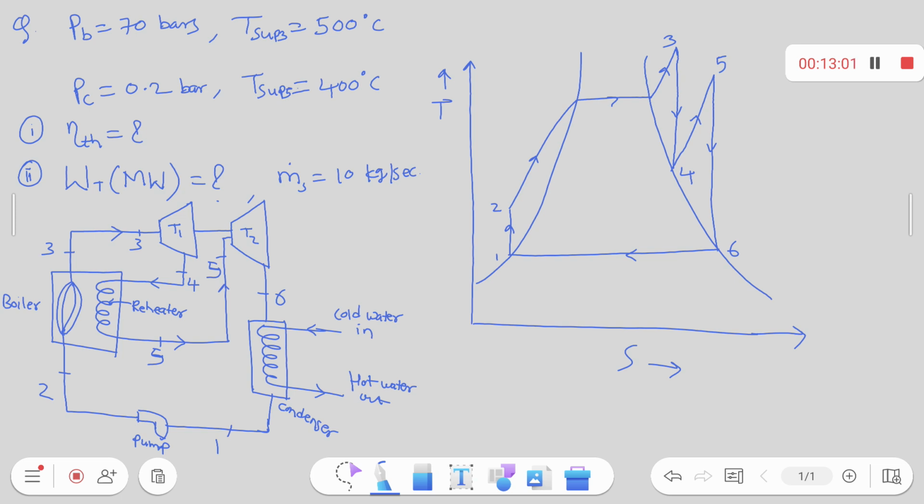all this is per kg, yeah? All this is per kg. We have to calculate enthalpies per kg and use them. Heat addition takes place from 2 to 3, so heat addition will be equal to enthalpy H3 minus H2, right? We have to calculate the enthalpies by using the HS chart and steam table, right? I have already told you to bring the steam table, okay? Up to here it is clear.